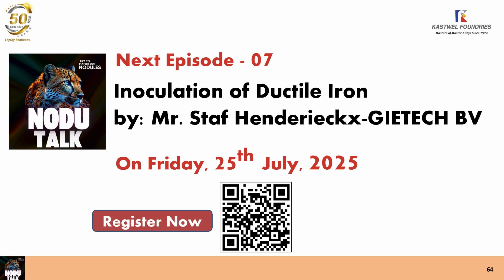Yes. Well, for the pouring temperature you have, of course, two different points. First, your metal should be liquid at the end of the pouring. And I should say not only liquid, but liquid plus around 30 degrees C above the liquidus temperature, so that when you stop pouring, the metal is still liquid all over the casting, not yet solidified somewhere.